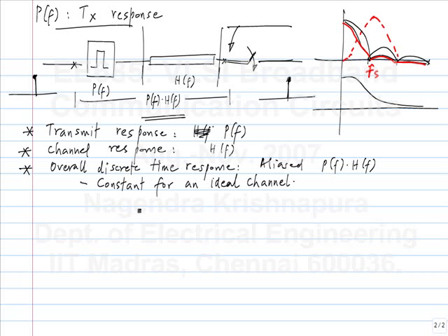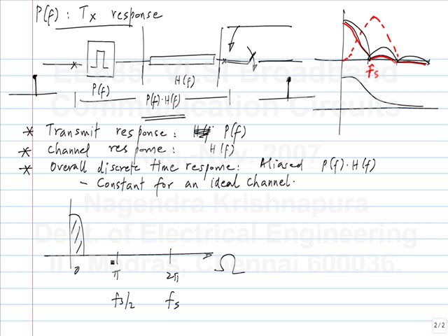What does low pass mean? So this corresponds to Fs. If you remember the large omega, which is omega times Ts, this is Fs by 2. In the case of a discrete time signal, a low pass signal means some signal whose frequency is somewhere here, and there is a very high frequency. The highest frequency that's possible is pi, right? That is the alternating sequence.